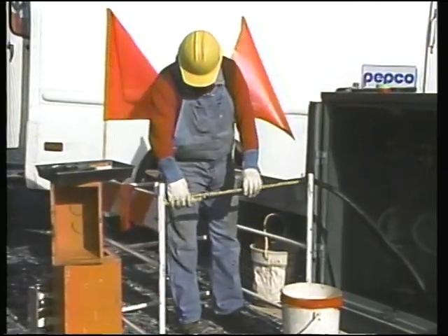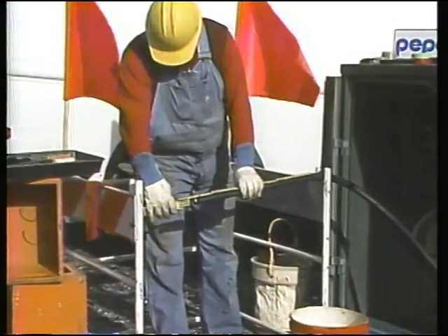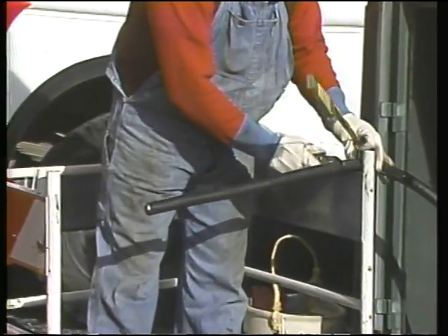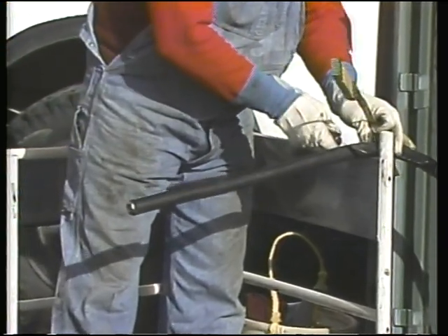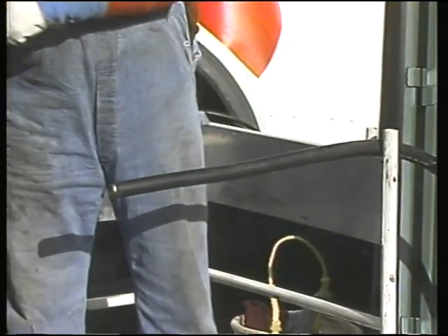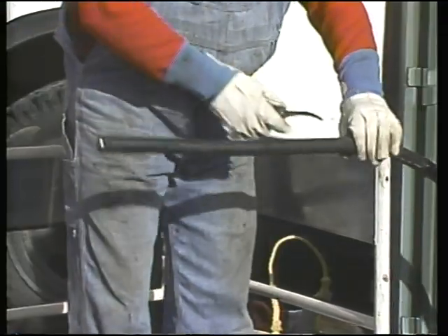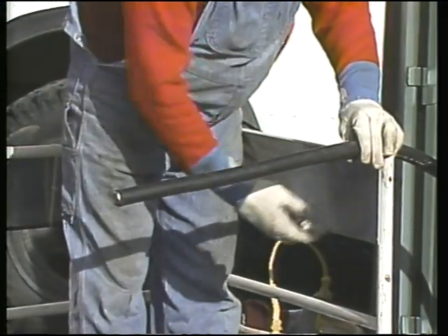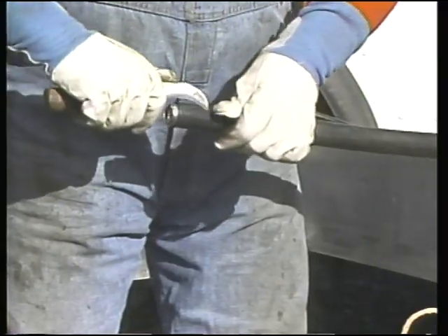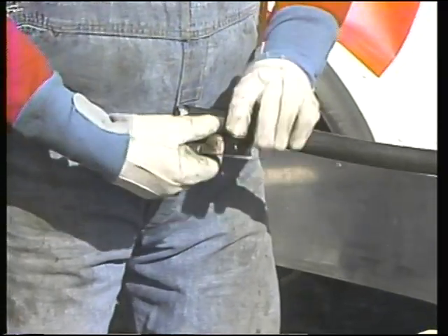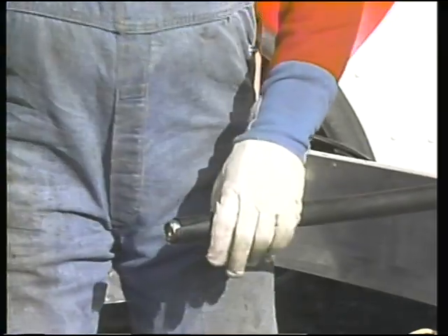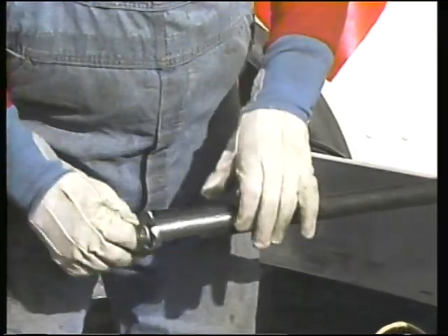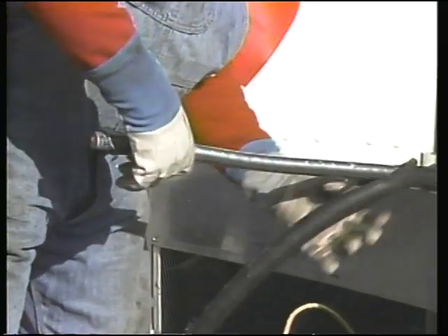For this example, the first layer to be removed is the cable jacket. The workman first measures the proper distance and places a mark on the cable jacket. He then cuts around the cable at the marked distance, being careful not to cut through the jacket to the layers beneath. After this is done, he slits the jacket from the first cut back down to the cable end. Once the cuts are made, the jacket is removed, exposing the metallic shield.